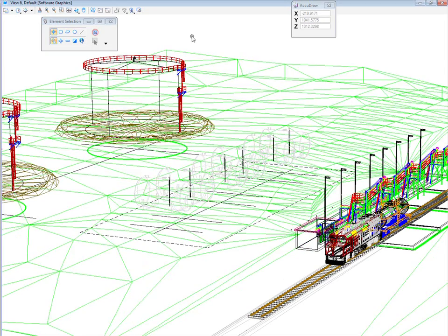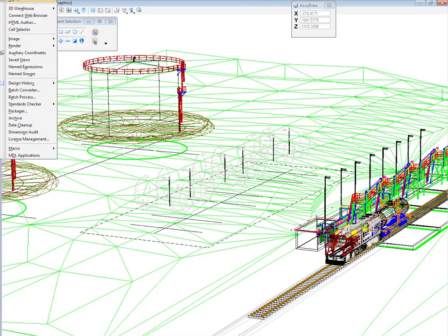Not only do we do that, we have display modes in MicroStation V8i. We can also render, and boy can we render. We'll be rendering to the point where everybody else will be like, why did I spend all that money on a package to render, especially when it was inside MicroStation? It's under Utilities. It's under Render. And in Render, you can see that we have a number of options. We can do luxology rendering. We can do a fly-through. We can do a solar study or an animation. We're going to be using luxology in this session. There's another way to get at this as well.